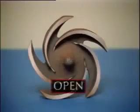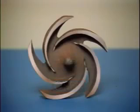With those types of liquids, an open impeller could be used. This is an open impeller. As you can see, this impeller has no shrouds to direct the flow of liquid. While this design helps prevent clogging, it's less efficient at moving liquids than a closed impeller, since the flow of liquid is not directed between the vanes.